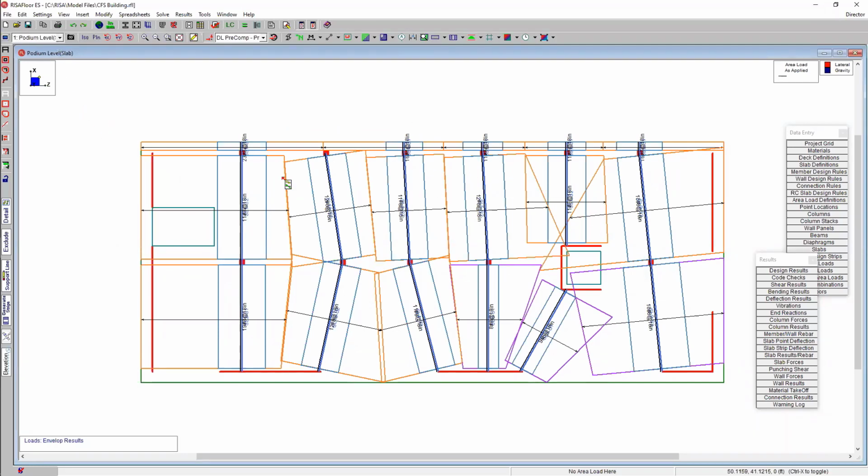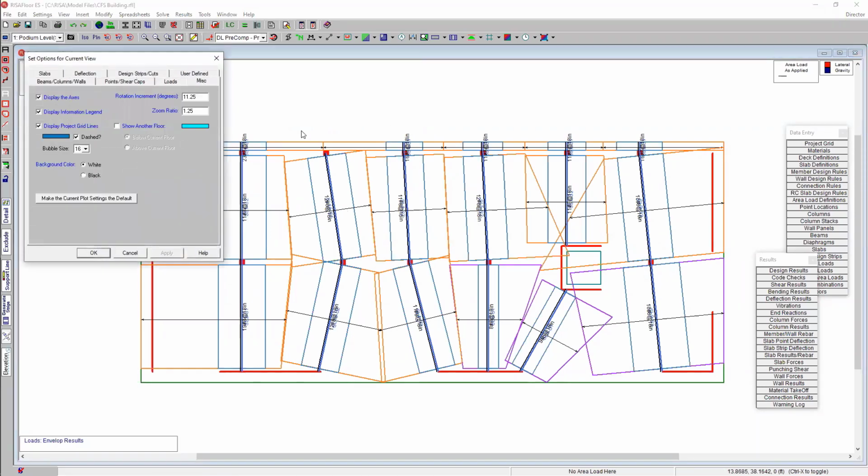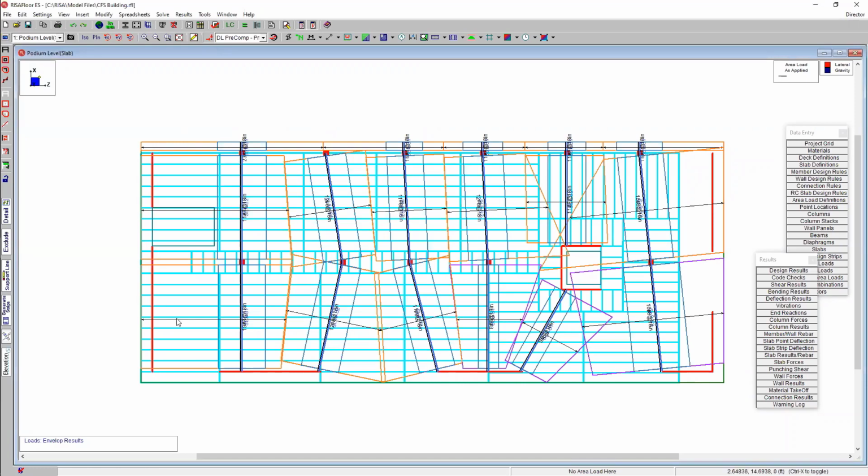So I have a two-way slab design here, and I'm picking up the loads from above. If you ever wondered how this lined up, I always like to see the floors above, and I show what it looks like as it sits on this floor. So this is a structural concrete slab that the rest of the structure is sitting on, and it's carrying the forces right from these walls into the concrete slab and then down to the bottom of the building.